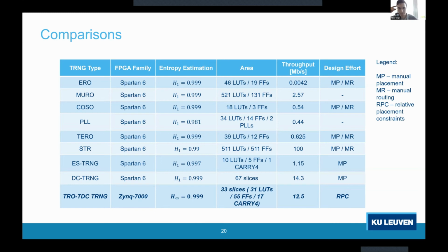Benedict, I would think the other way around. Why do people use pseudo-random number generators? Because it's very tough to generate true random numbers at a high throughput. So that's why people go to the pseudo ones. But with the architecture here, you can get high throughput with the correct amount of post-processing, so high quality with high entropy. You could go for extremely lightweight post-processing if you need it after that.